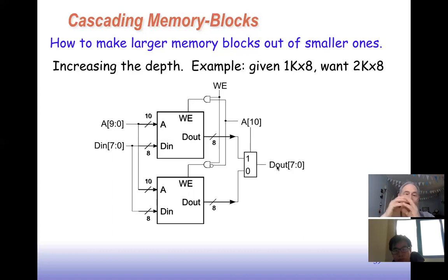That's the reading. And the writing, similarly: what we need to do now is take our write enable signal and AND it with this address line. So we're going to write enable the proper memory block based on what this address bit is. If the address bit is a 1, that ANDed with write enable when we're doing a write will produce a 1 for the write enable into this block. If it's a 0, then we'll activate the bottom block. That's why there's a bubble there.